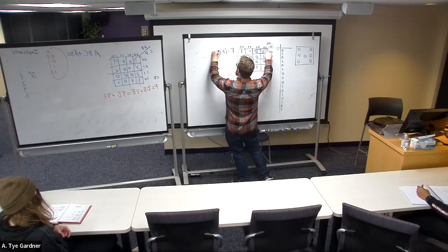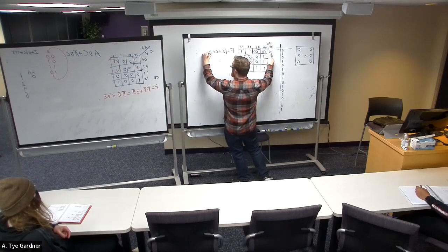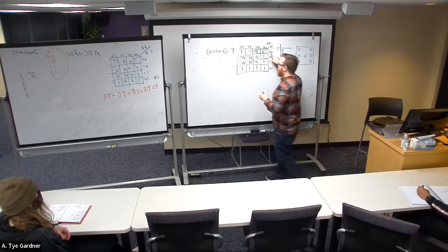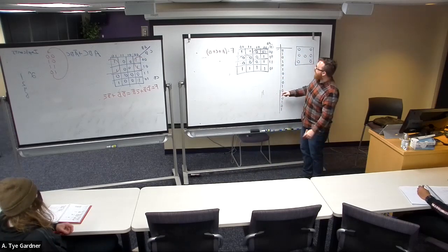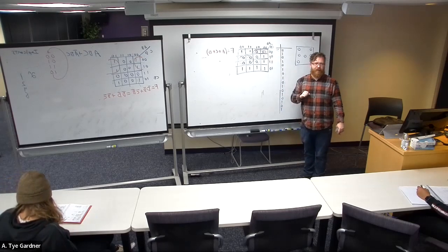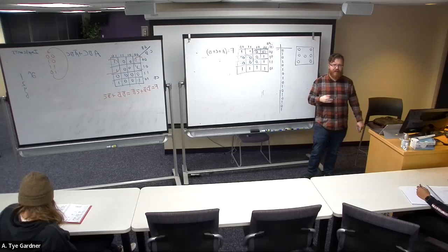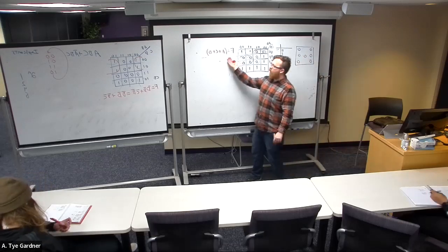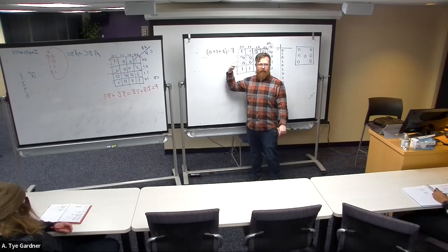A or C or D. No bars, because they are all 0. That's where most of the confusion comes in. Most of you will get the form right, because remember this is product of sums, but you'll forget to flip the variables as well as the gates.